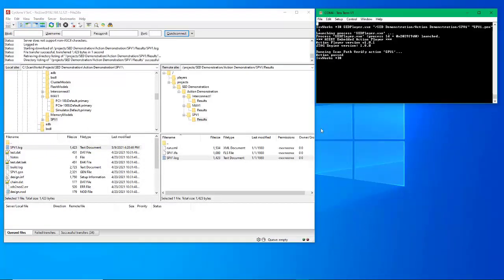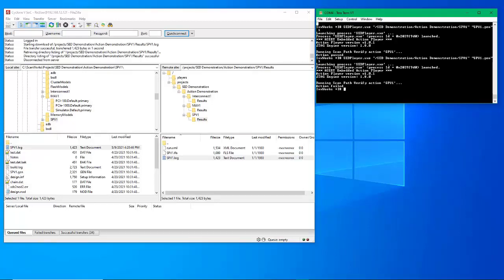Now I'm going to flip the switch, which will break the TDI TDO shift path, and I'm going to run the test again. Again, I'm just doing all of this through the command line, but these tests could easily be automated and run on the SoC on your board, or service processor on your board, at different intervals. So I will run this test again, and we can see that the test action failed.